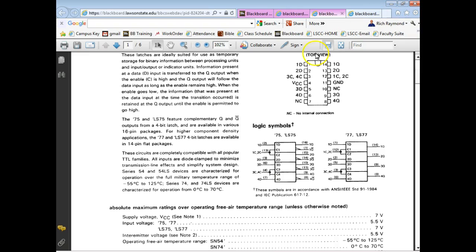I see. So this is an international symbol. Okay. And notice what they do for low active outputs. They put that triangle thing on there. I don't like these things. So if they did a 2-input AND, it would be a square, and it would have the AND in there, and then it would come straight out. If it was a NAND, it would have that triangle on there. So international symbols, all your basic gates are drawn in squares.